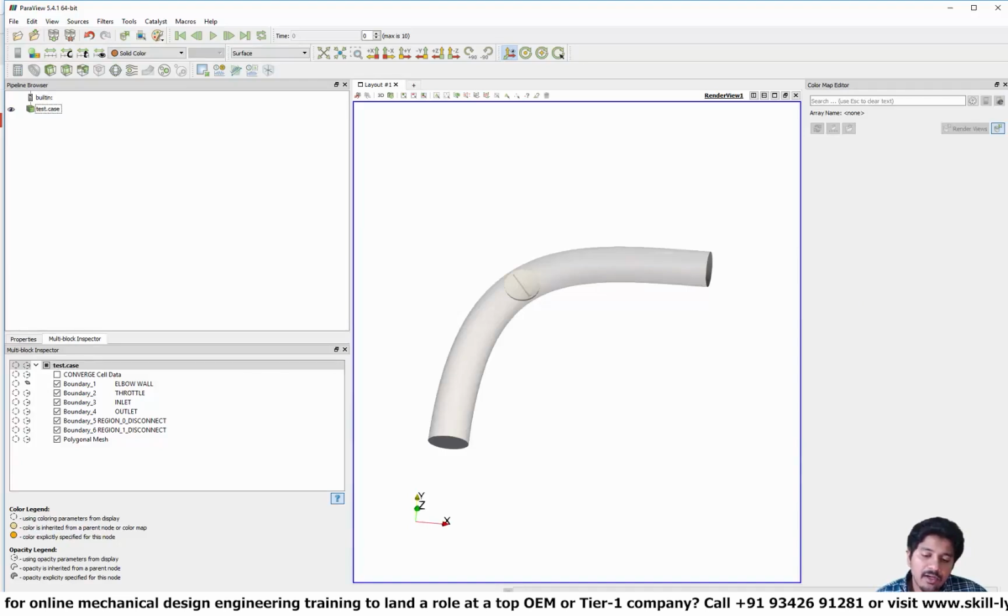So the idea behind streamlines is to visualize how the flow takes place, and to understand that, let me give you an example. Imagine that there is a river and you put some paper particles in the river, and if you keep on taking pictures of that paper particle, several times a second, and if you put all those pictures together, you can actually track how the paper moves, right? So that is a path line, right?